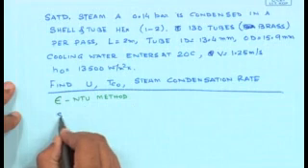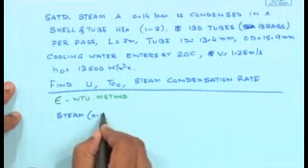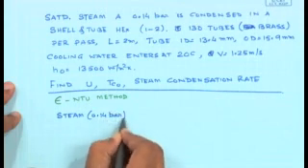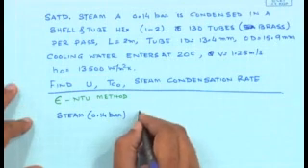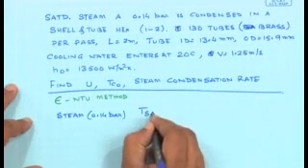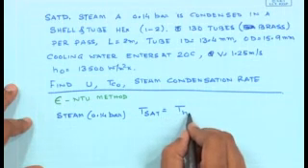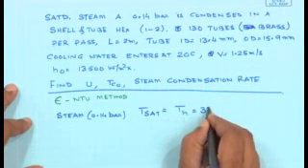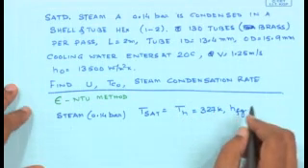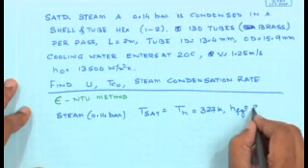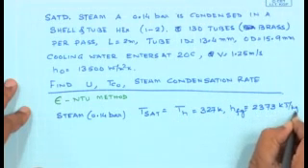So for the steam which is saturated at 0.14 bar, you can get the temperature from the steam table. Tsat, the temperature of the hot fluid, which is the same at the inlet and outlet, is 327 Kelvin. The value of the latent heat for condensation is 2373 kilojoule per kg.